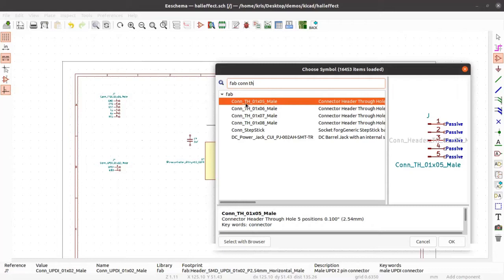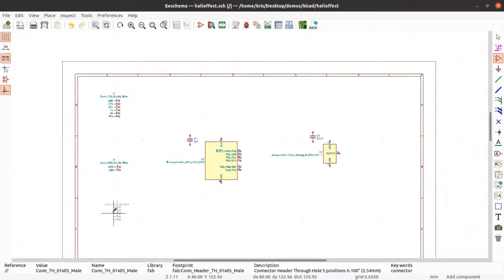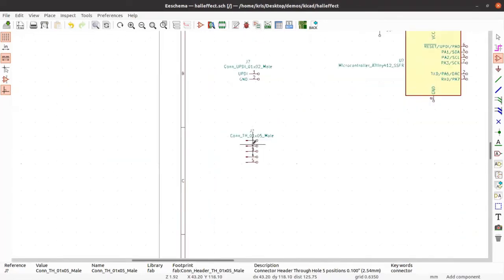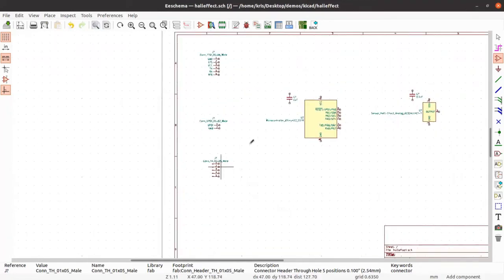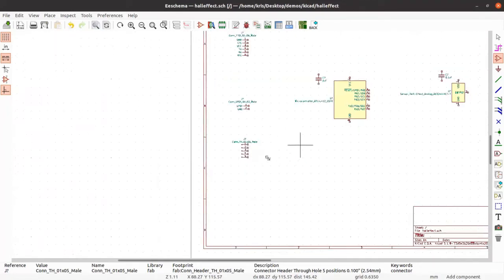I'm going to put a bit more energy into this, but at the moment I have added these 4, so 5-pin, 6-pin, 7 and 8-pin through-hole connectors. I think it's going to make everything from 2 to 16, but you can select one of those, and they have already associated footprints for the through-hole headers.